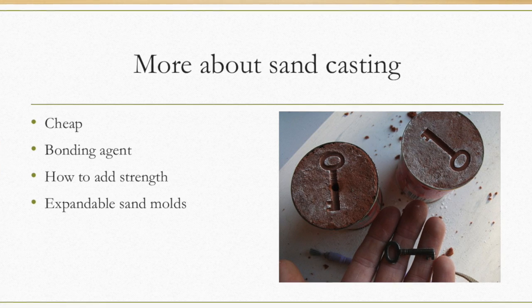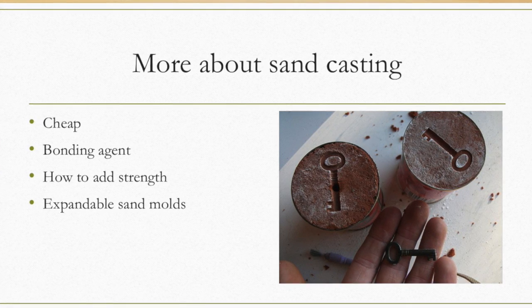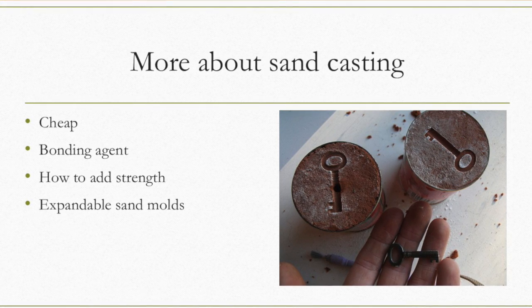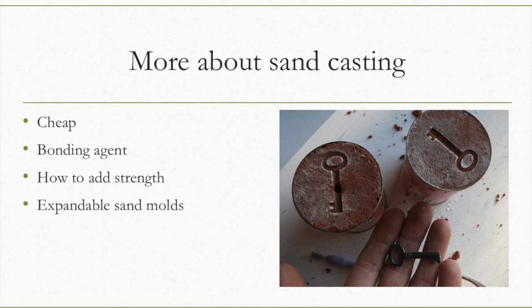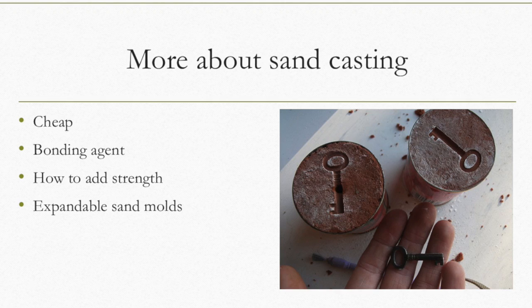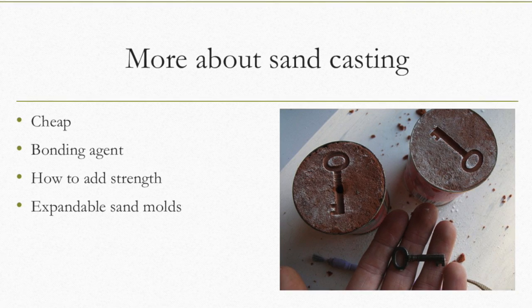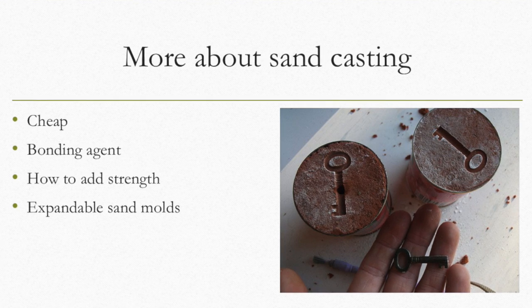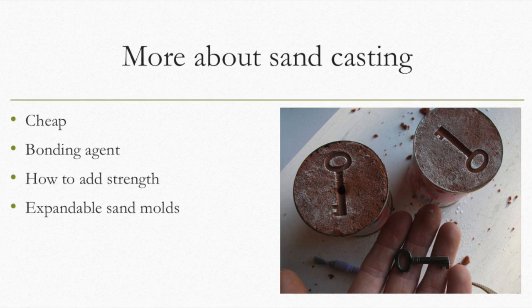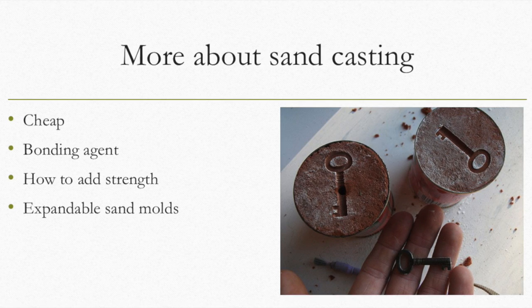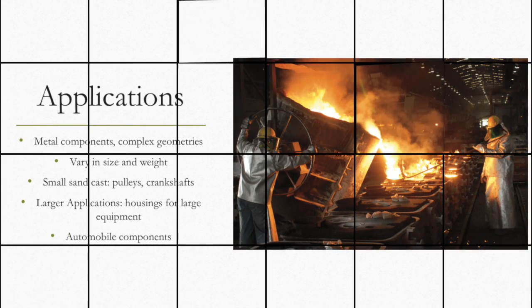Sand casting utilizes expendable sand molds to form complex metal parts that can be made of nearly any alloy. Because the sand mold must be destroyed in order to remove the part, called the casting, sand casting typically has a low production rate. The sand casting process involves the use of a furnace, metal, pattern, and sand mold. The metal is melted in the furnace and then ladled and poured into the cavity of the sand mold, which is formed by the pattern. The sand mold separates along a parting line and the solidified casting can be removed.